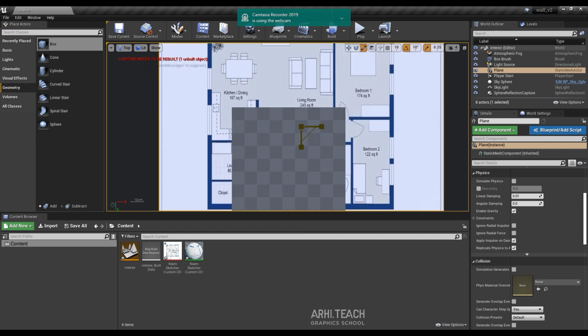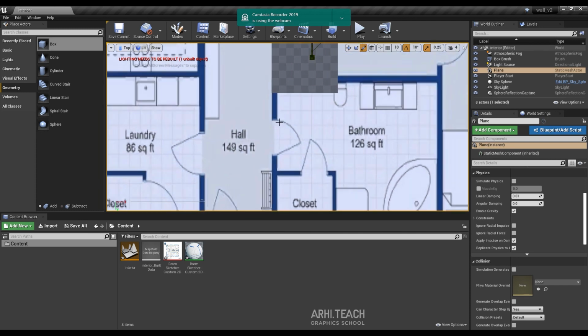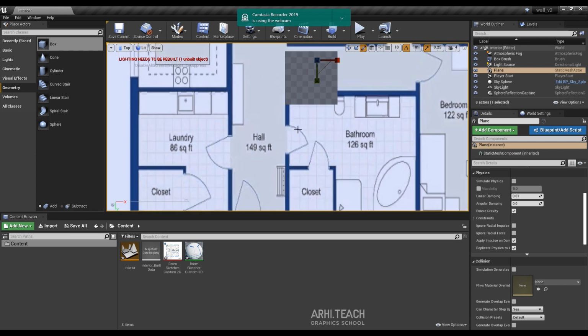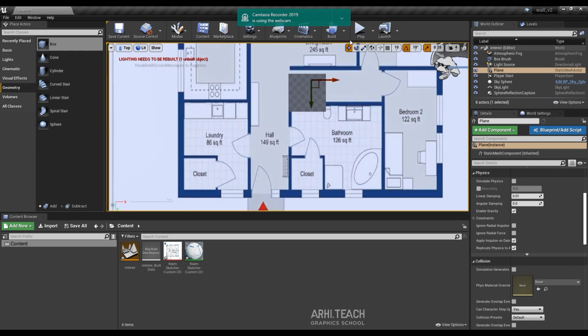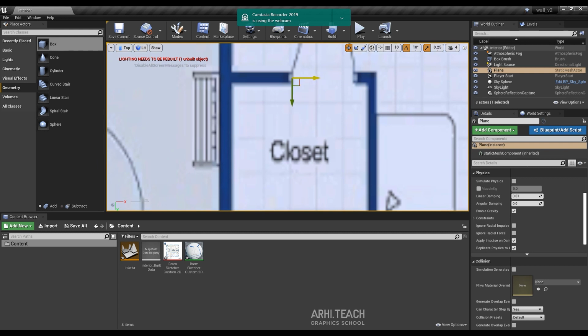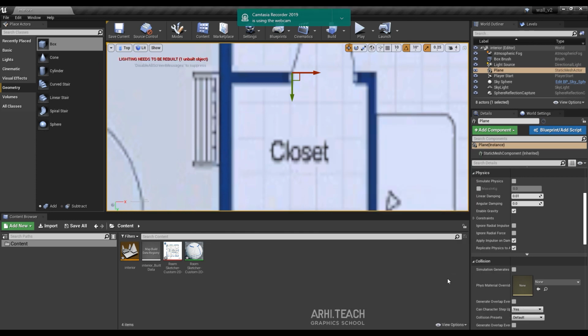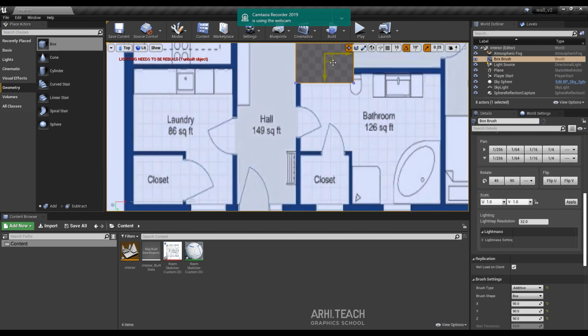And here's an example. These two doorways are conventionally located side by side, both 900 each. How to align them? I click on the Moving tool. You can just click here, select the plan, hold Alt, hold the scroll, and now I start to transfer the pivot. For example, here. Now it's transferred. To fix the position, right-click, pivot, set as pivot offset. Done. Now we drag our overall box, put it here in the corner where we have the pivot of the plan,